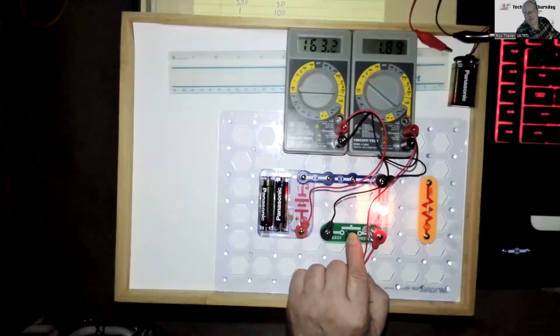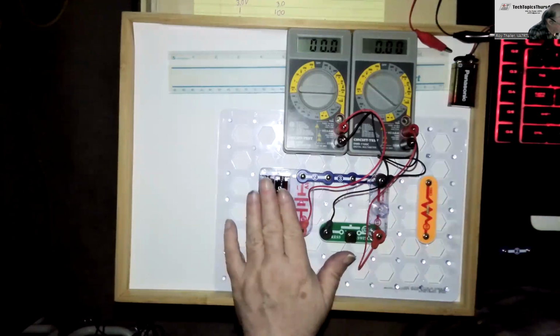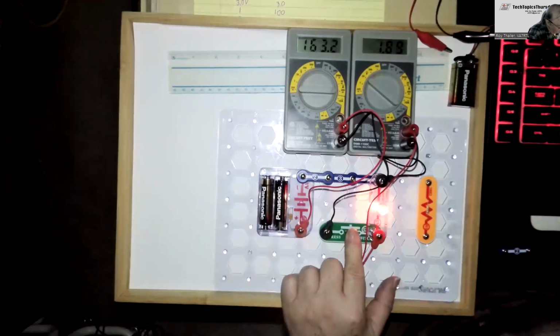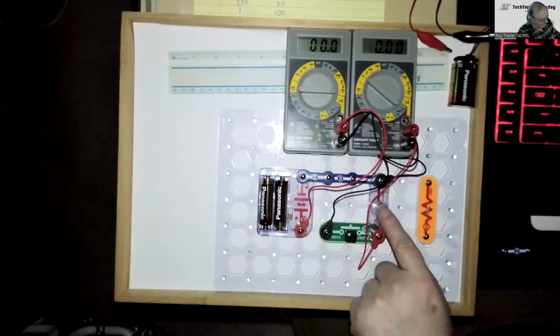So it's telling me that it's using 163 milliamps. And the voltage has dropped a little bit because the battery is dropping on the load. But that's nowhere near the 1 amp or 1.5 amps that I was expecting. Now the reason for that is that the lamp is actually a non-linear circuit. The resistance changes, so it starts off with a high resistance and becomes a low resistance.